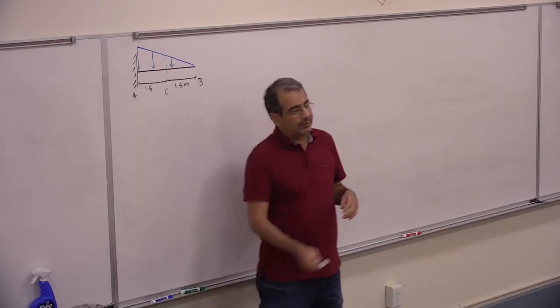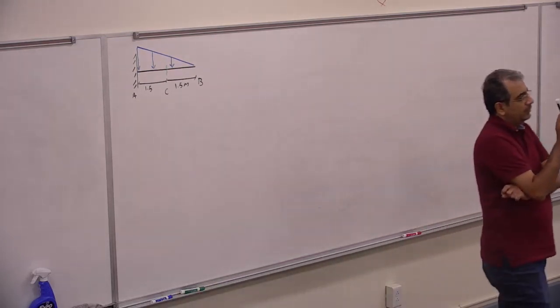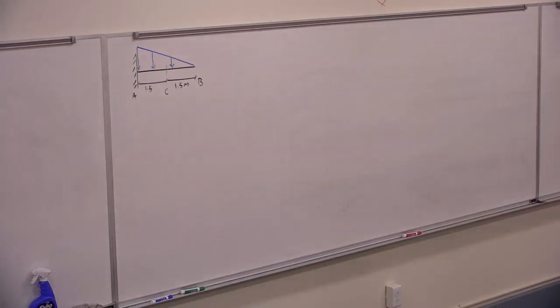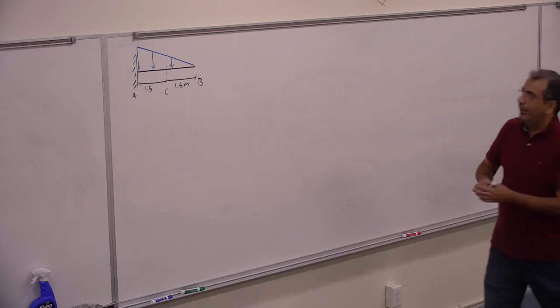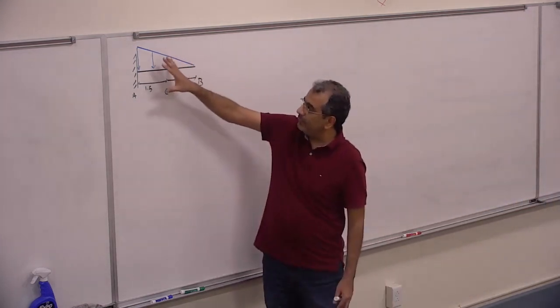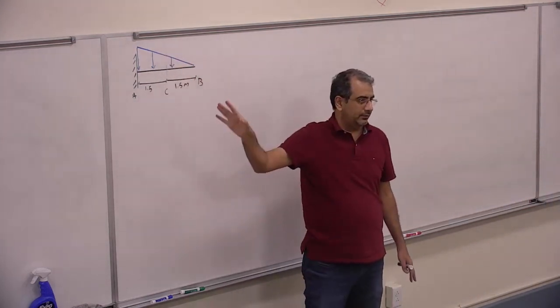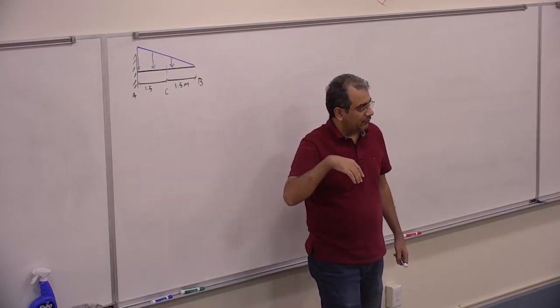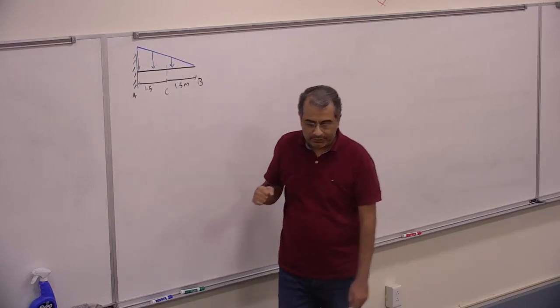The other point was that remember I said when we are calculating the internal force, if there is a distributed load, do not touch the distributed load until you cut it in half. Okay? If there is a distributed load, do not touch it until you cut it in half. So I'm not going to replace that distributed load with a single load yet. I will cut it in half first, and then I will do that.